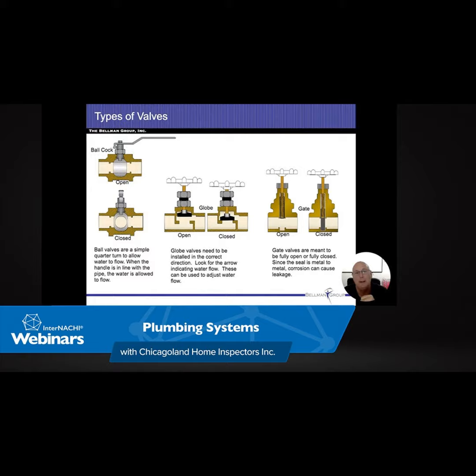But an S-trap, you can see how it goes down, up, and down. If I get enough of a water flow, that can create a siphon. And if I pull everything out of the bottom trap, then I'm going to let soil gases come into the house. Solution, turn the water on slowly and fill it back up again for a few seconds, and there won't be any smell. The middle one is what we call a crown vented trap.